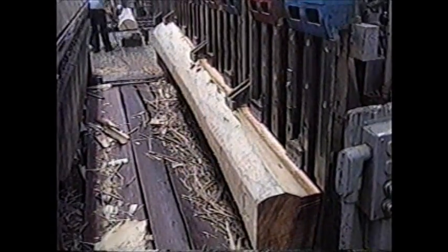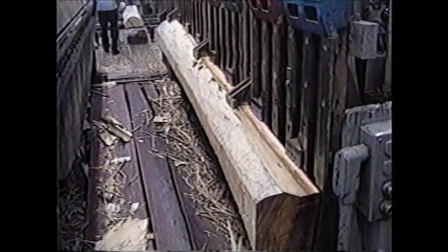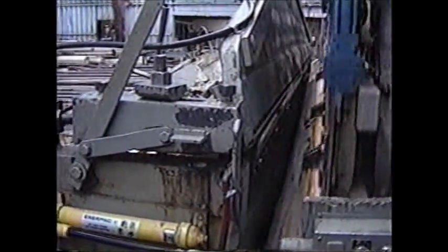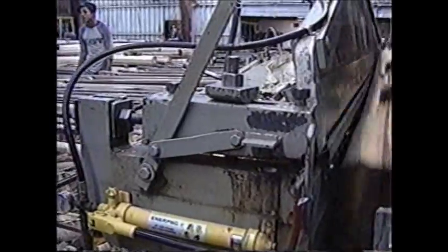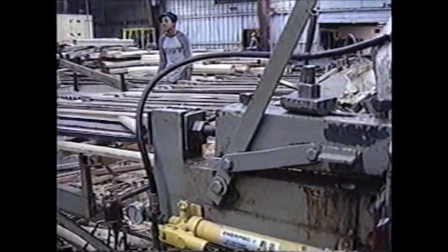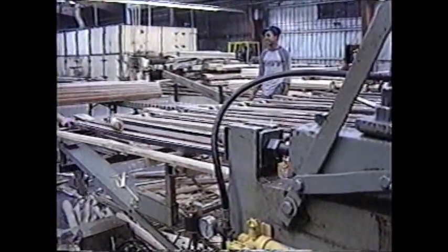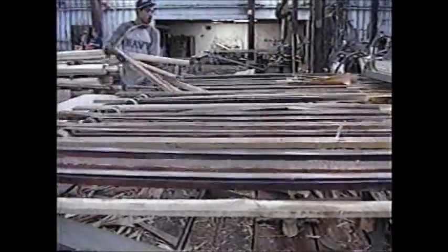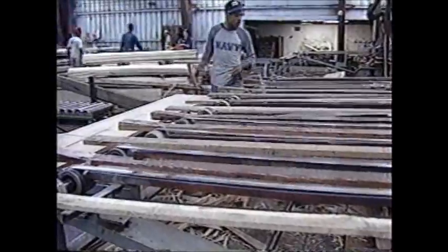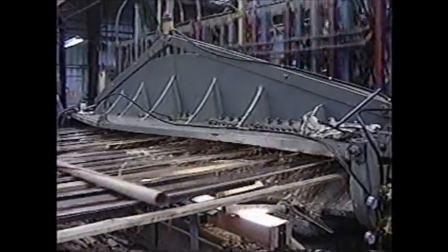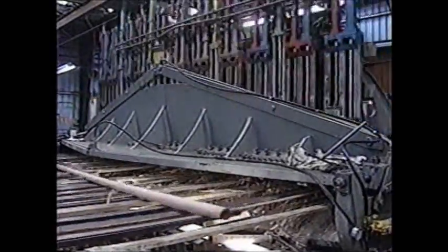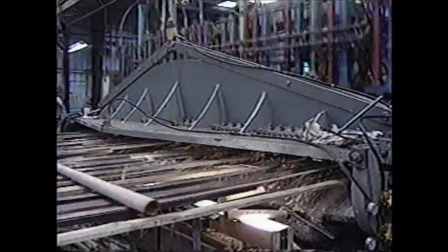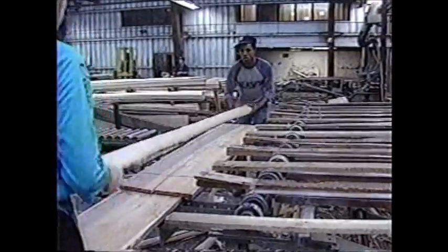Flitches are gripped by chucks on a vertical slicer. The slicer produces a piece of veneer on each downward stroke into a razor-sharp knife. The veneer cut first is again discarded until sheets of usable size and quality are sliced. These slices are so thin, they tend to curl. The heating and soaking process makes the thin veneer very flexible.